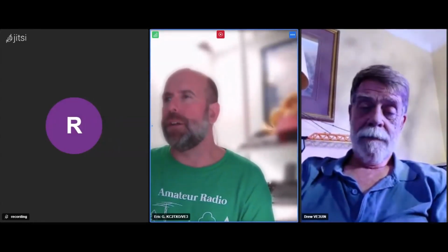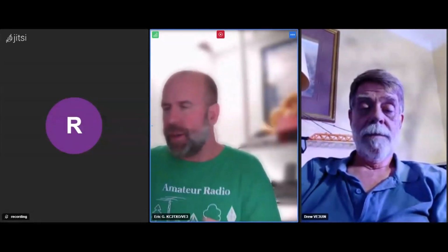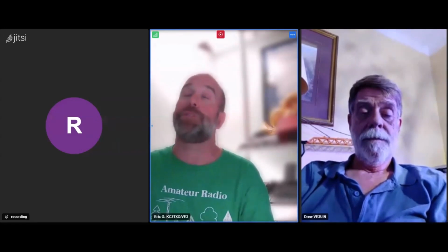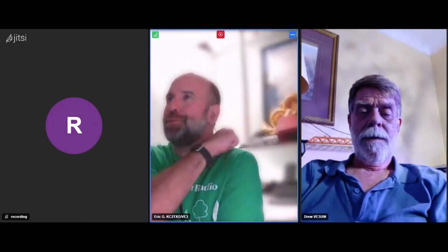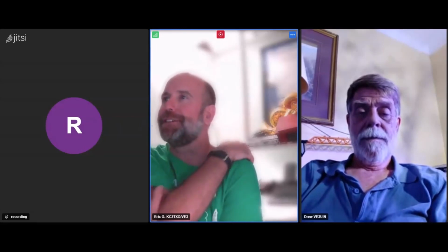Right. Like after Field Day, I participated in the contest on the 1st of July. And I even reoriented, I assumed that the end fed half-wave radiates off the sides. So I had it basically east and west, trying to get Canadian stations. And I even suspended in the air the end where the matching box is. And oh man, that was so disappointing. I think I made 3 contacts on the Canada Day contest. It was just so, and they were a struggle to make too. So I know something is up.